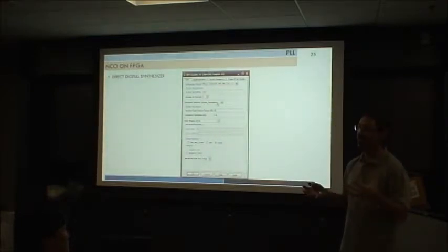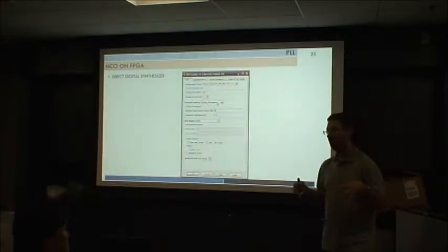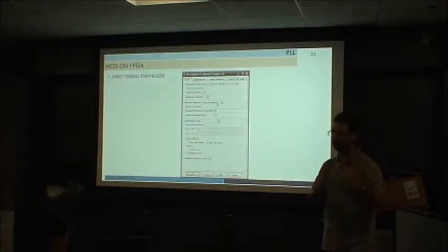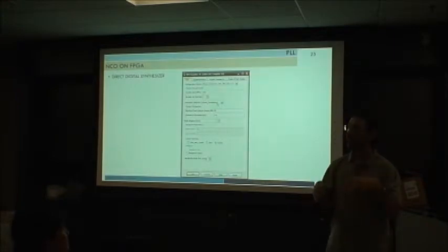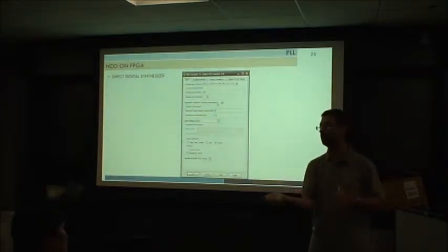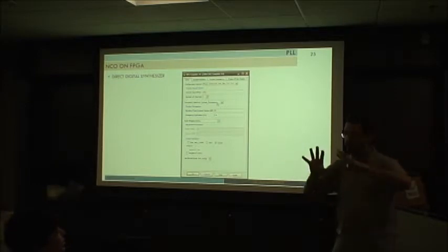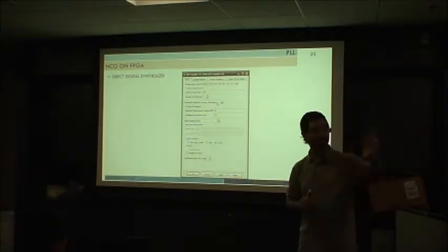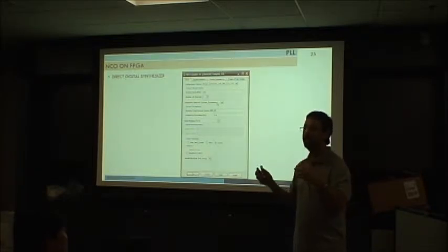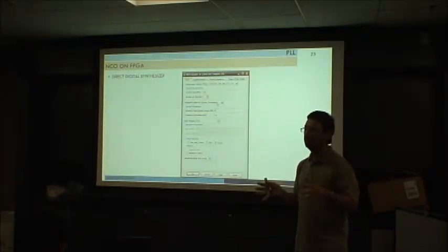What is System Generator? It's exactly the same as Simulink, but instead of placing blocks, let's say an adder or a multiplier or whatever, you place exactly the same blocks, but at the end when you compile, that's translated to VHDL. So you make whatever your system is there, all with these blocks from System Generator, and when you compile it will create a VHDL file, basically.